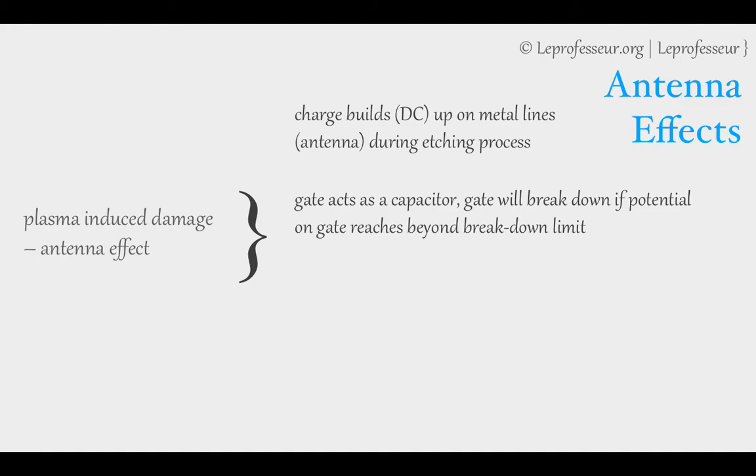Those are technology specific questions. One needs to look into the technology data sheet and understand other technology parameters. But remember, in simple form, if too much charge is accumulated and there is no sink provided for that charge to go off from the gate, it will break down the gate capacitor. Simple as that. And once the gate is damaged, it cannot be repaired.